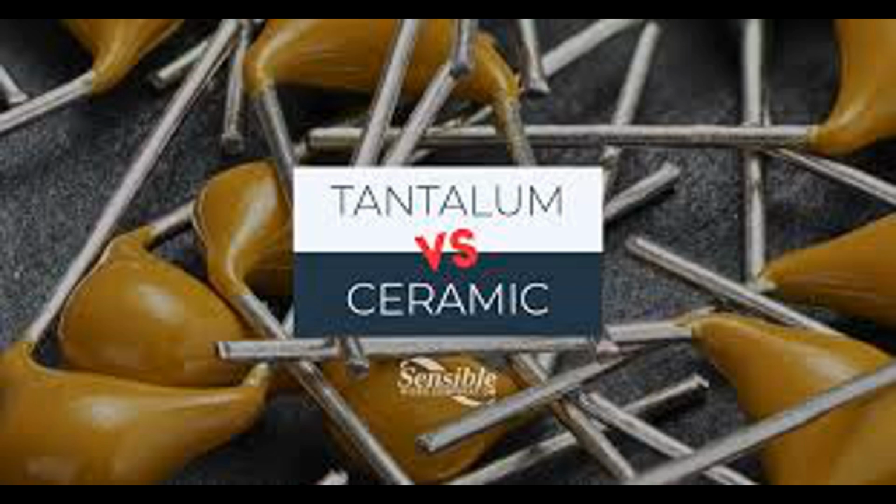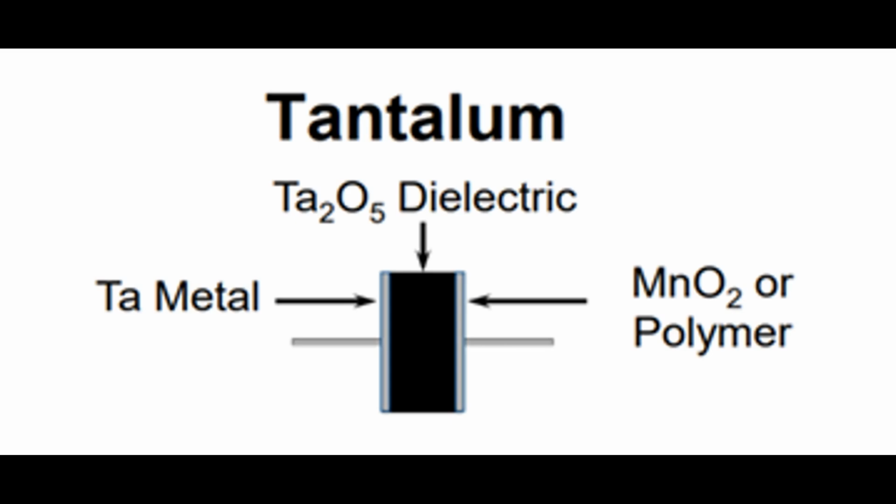2. Long-term stability and reliability. Stable capacitance. Tantalum capacitors maintain their capacitance values consistently over time, with minimal drift or degradation. This makes them highly reliable in applications where stable performance is critical. Low leakage current. They have low leakage current, meaning they retain their charge well over extended periods. This is beneficial in battery-powered devices, where energy efficiency is essential. Durability. Tantalum capacitors are known for their robustness, especially in high-stress or harsh environments, including high-temperature and high-humidity conditions.